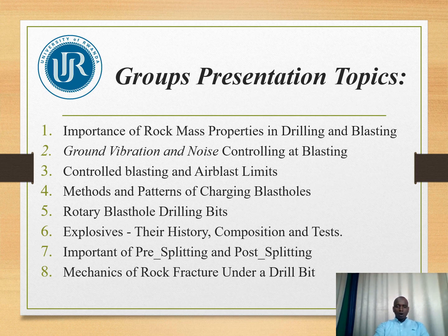Also important are pre-splitting and post-splitting. Pre-splitting is actually controlled blasting, and then the post-splitting. So you should identify the importance of them, also the mechanics of rock fracture.